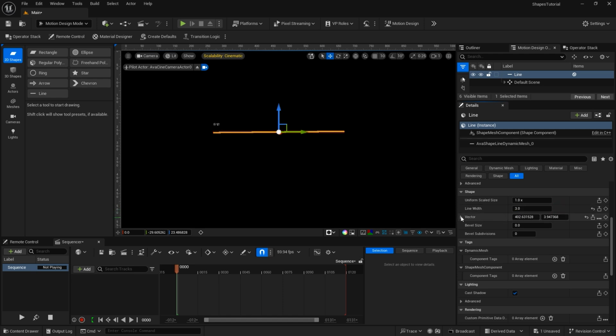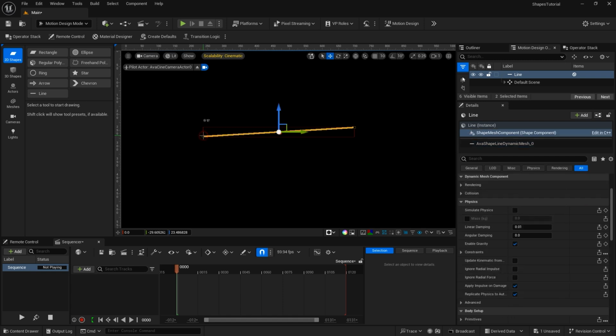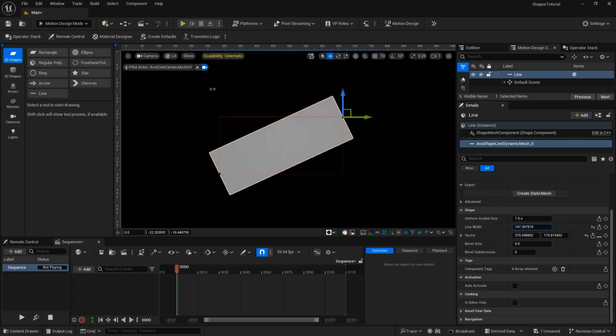And then on our vector options here, that is what creates the line. So I can adjust those, the length of it, or this angle here. I can also adjust these by going to the line and selecting these little points right here. It takes a little bit of work to get them just right. Once you have them, you'll get this handle that you can move this around with to reshape the line in the direction that you want it to go. If you have a good amount of thickness to this, you can also bevel the edges.